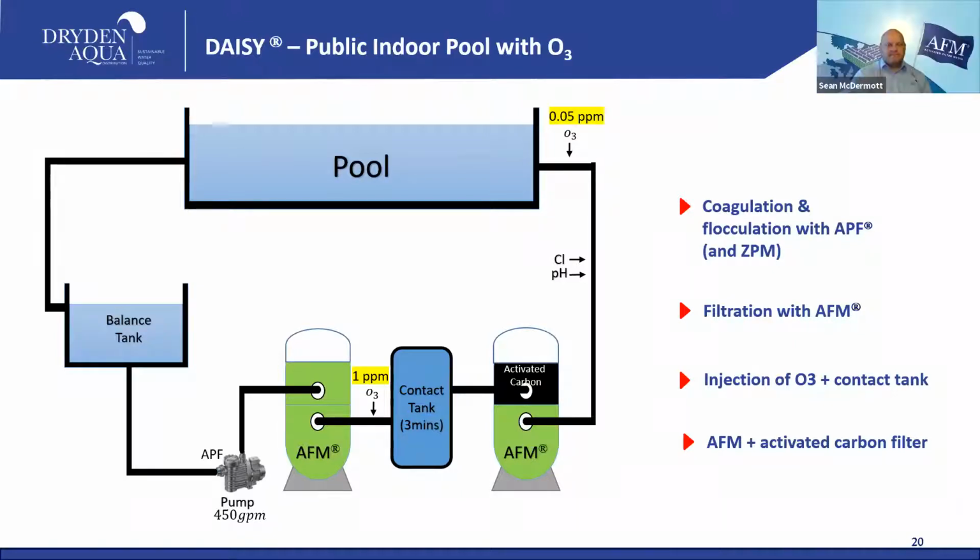Right. If you do that, honestly, I would dose the ozone just in front of the pump, so you have a longer reaction tank. But yeah, that's another one. It will not make such a big effect on the combined chlorine. Yeah, that's what I think. So it's more for disinfection. Yes, it will make an effect, but it will not bring it from 0.4 to 0.2. Yeah. Right. Okay. Definitely not.